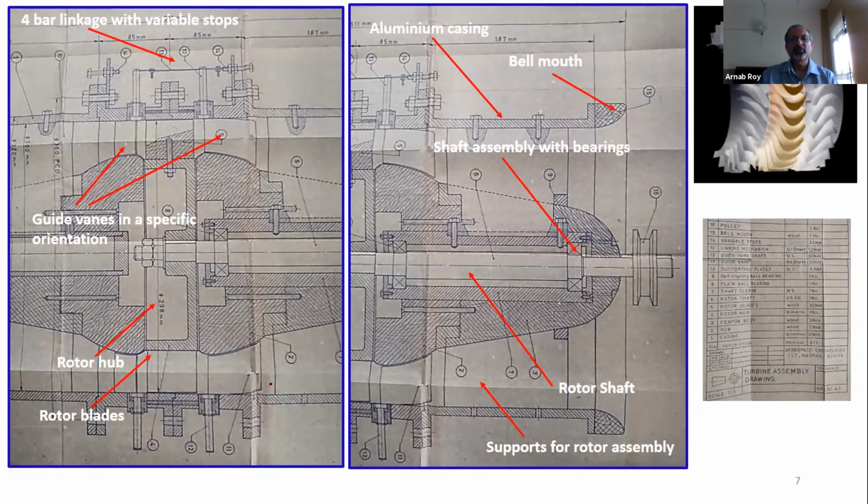So here we are trying to look at some of those old drawings where we used to do it on a drafting board. And here you can see some parts of self-rectifying air turbine, which we had built in a laboratory at IIT Madras to see for ourselves how these turbines function and try to quantify its performance. So here you can see that you have the rotor shaft carrying a large number of blades, and which are mounted on the rotor hub. There are about 50 odd blades, and the blades are located here.